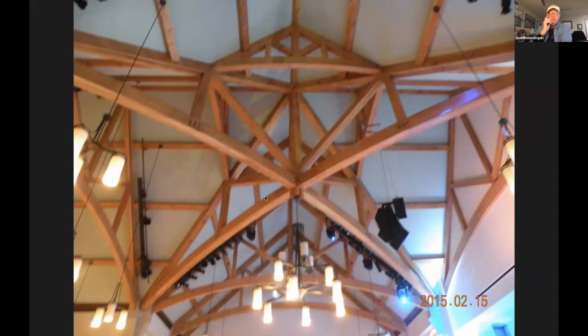No, when you're checking for radial tension, there's a fairly simple formula in the Timber Construction Manual, 6th edition. I'm not going to look it up right now, but if you look up radial tension in there, it'll give you the formula, and you just simply put in the radius of curvature and the size of the member, and that formula will give you a value that has to be less than a controlling or limiting value. I think that's about as complex an answer as I want to get into at this stage of the game.